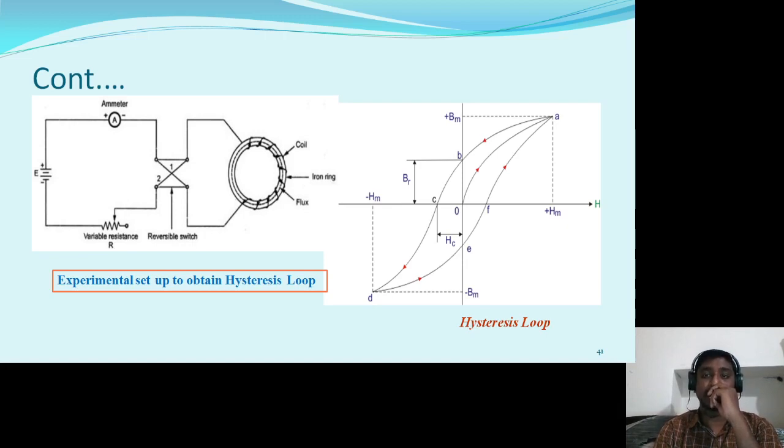So what about the magnetic flux density? It goes on decreasing. The B to C portion shows that the magnetizing field strength H increases, but in the negative direction, which shows on the minus X axis. Coming to B, it reaches the minimum position, that may be 0. Right? It's not 0, it starts decreasing. So at point C, the value of H becomes negative. At point C, the value of H is negative, which is known as the coercive force.